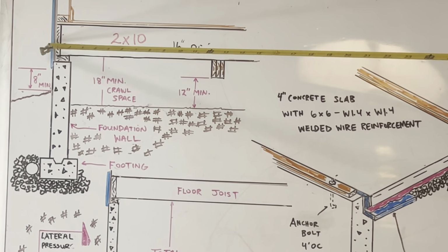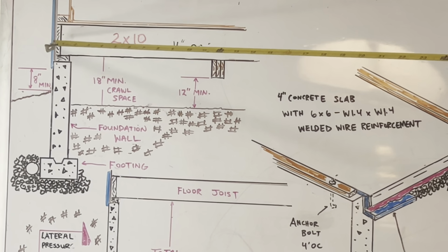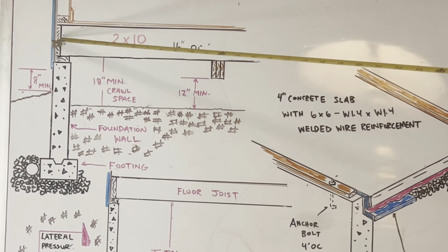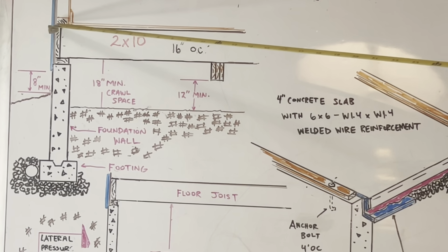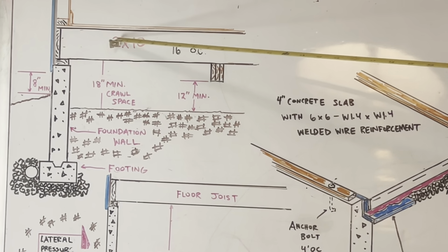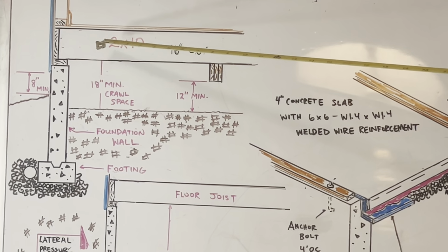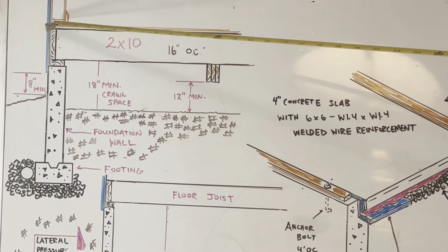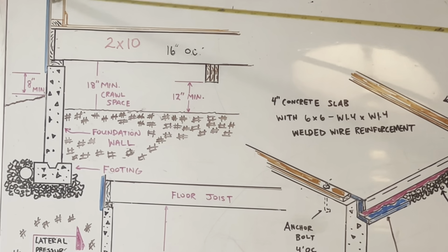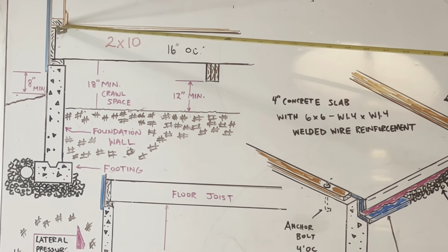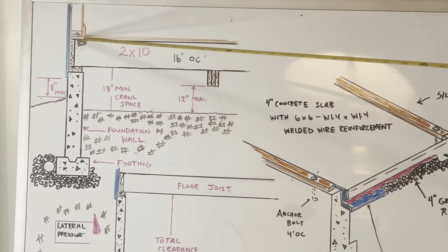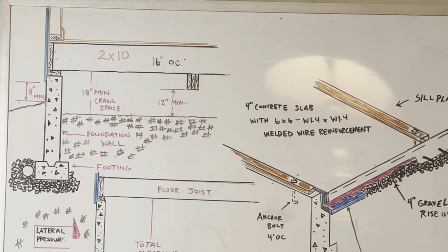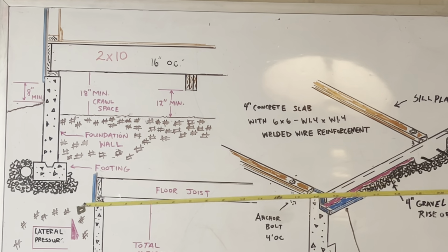But if you look right here, this is the end grain for what you'll call your band joist or your rim joist. Okay, as we keep on going up here, of course, you're going to have your OSB decking on top, or it can be plywood decking. Okay, and here goes your wall, which is going to be your bottom plate. Then you got your studs right here. And you can look at the profile right here on my baseboard. Okay, I got my sheetrock and baseboard. You got a finished floor right here too. Okay, you got to be able to identify all of this, okay?